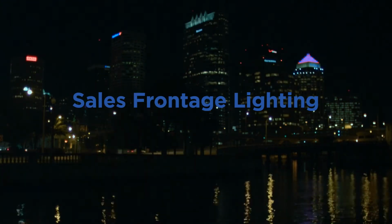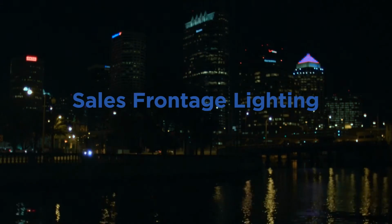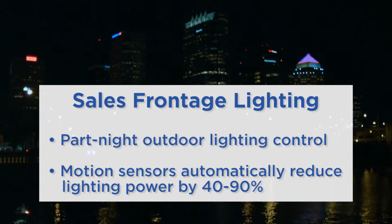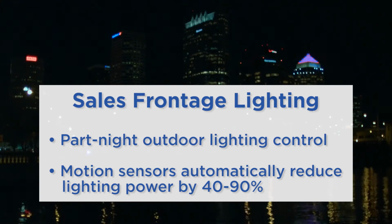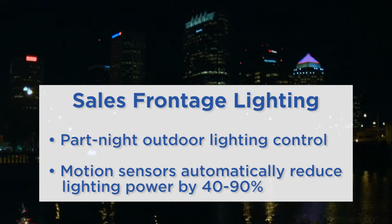Now let's review the outdoor lighting control requirements for a few specific outdoor applications contained in the energy standards. For outdoor sales frontage lighting, an automatic lighting control must be installed that meets the following requirements: a part-night outdoor lighting control, or motion sensors capable of automatically reducing lighting power by at least 40% but not exceeding 90%, and which have auto-on functionality.